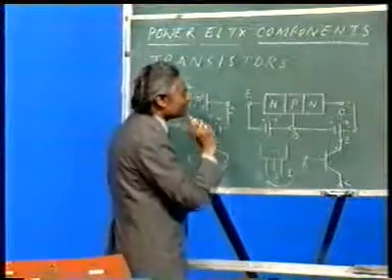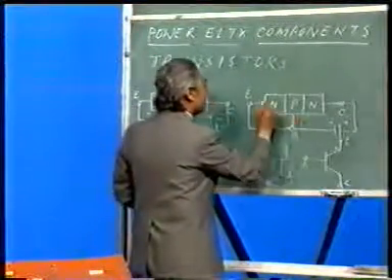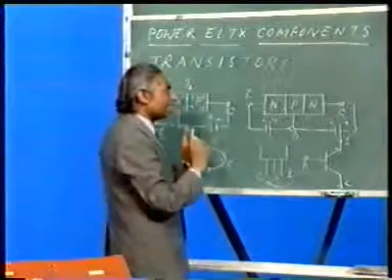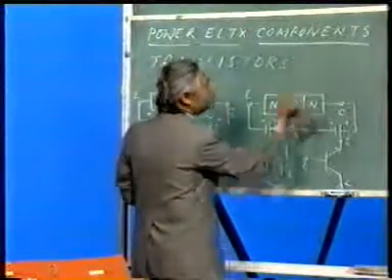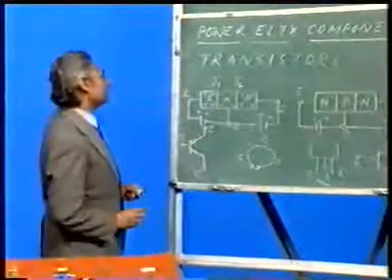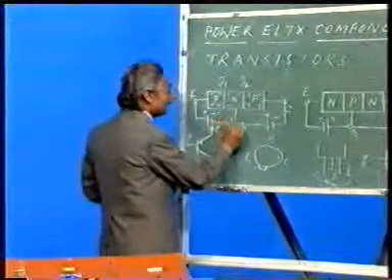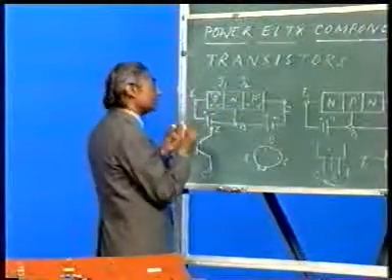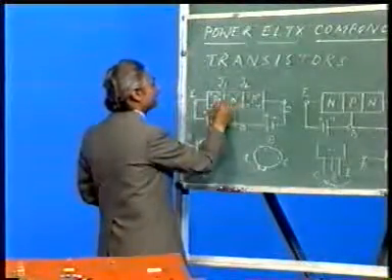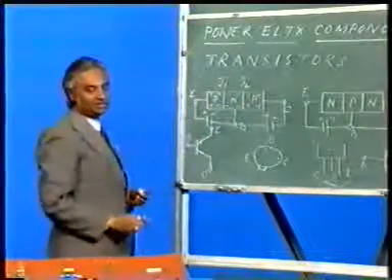If I have connected positive of my multimeter to base and negative to emitter and it conducts, that means the base is positive, and it is nothing but an NPN type of transistor. Reverse is the condition here. If I put negative of the multimeter to the base, positive to the emitter, and the device conducts, then it is N base, that is a PNP type of transistor.